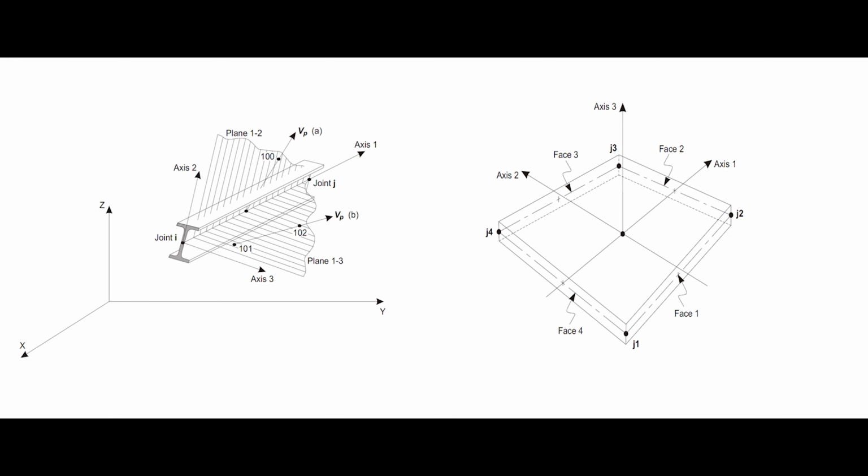The advantage of using line or shell elements for the estimation of building structural behavior is not only to minimize the total number of degrees of freedom, but also that the interpretation of the structural analysis results from line or shell elements is much easier than that of brick elements. The structural analysis results from line or shell elements are so-called member forces, which most of the time are easier to use for concrete or structural steel design than the stresses obtained from brick elements.